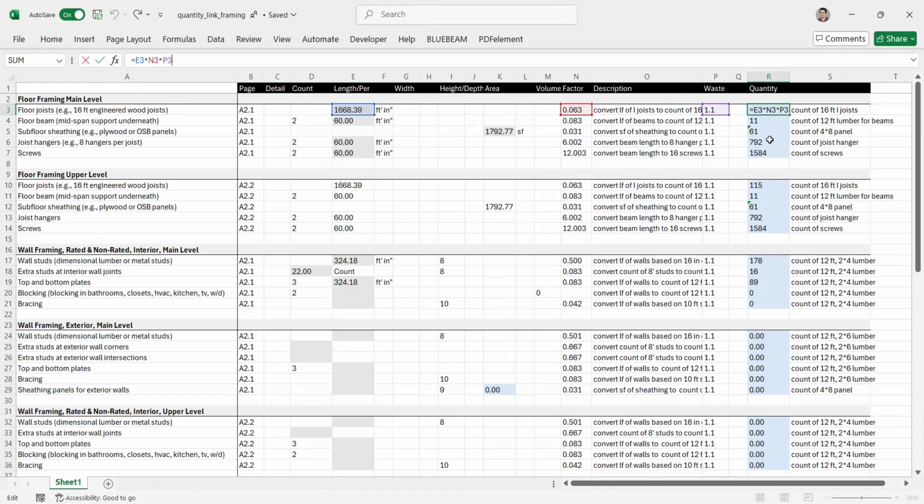So I don't want to deal with a lot of calculations here. So if I can find the right factor, just like I do it for waste, that's the 10% factor, it makes it easier for me to get that total number. So I first get the length from my markups, and then this factor, it is 1 divided by 16.